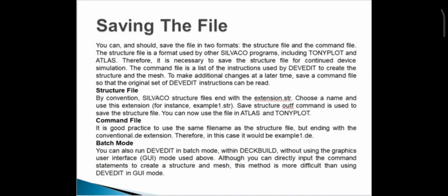example1.de. Batch mode. You can also run DevEdit in batch mode within Deckbuild without using the graphical user interface mode used above. Although you can directly input the command statements to create a structure and mesh, this method is more difficult than using DevEdit in graphical user interface mode. Using DevEdit in batch mode, you cannot call the structure by using the Atlas command. So we are using the graphical user interface mode to call the structure in the Atlas command.